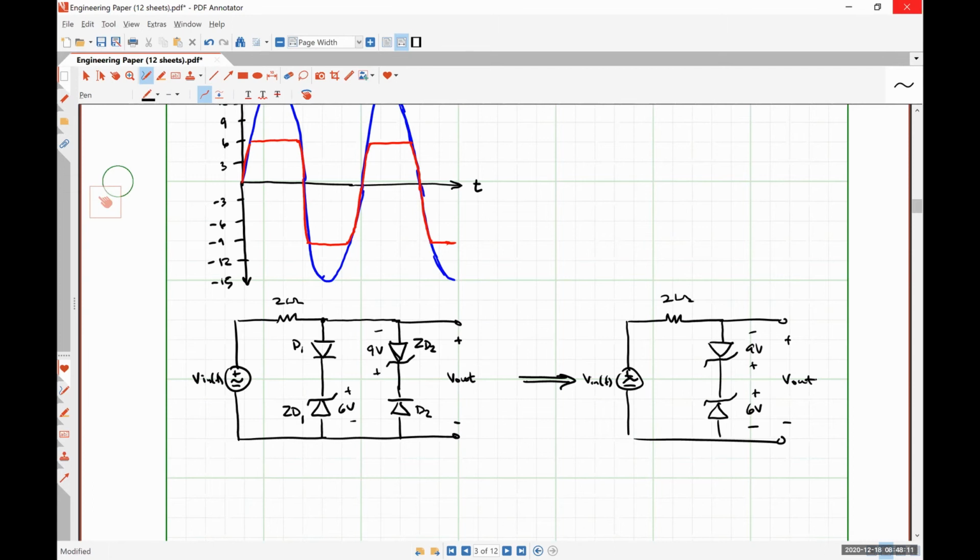In limiting circuits an awful lot, but the place that I personally saw them first is the output stage of a guitar's distortion pedal. So effectively, what something like this does, if you have an effects pedal and you feed in a sinusoidal signal of a certain scale, is cut off the tops of your sinusoidal peaks, both the positive polarity peak and the negative polarity peak.